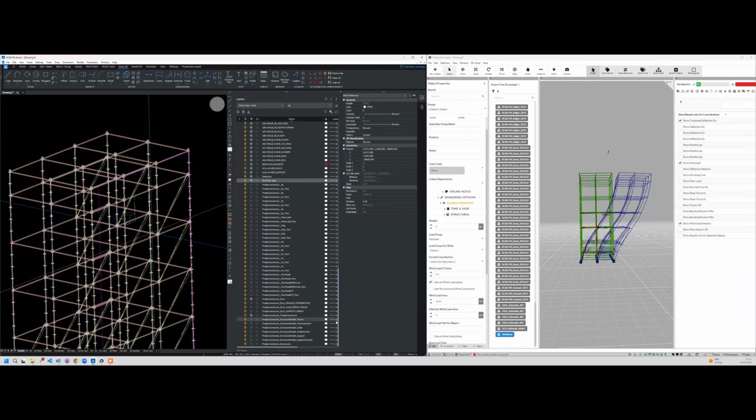One word about the accuracy of the calculations. Production Assist is a tool. In other words, Production Assist doesn't know what you're doing. So it's really easy, especially when you're doing outdoor wind calculations, to get something wrong. A typical thing is the CF value, because it is not really natural to people that are not involved with structural calculation on a daily basis. So if you type in the wrong CF value, you can get into a lot of trouble. What we recommend is, if you're not really sure how structural calculations work, I would always ask an engineer to check this.